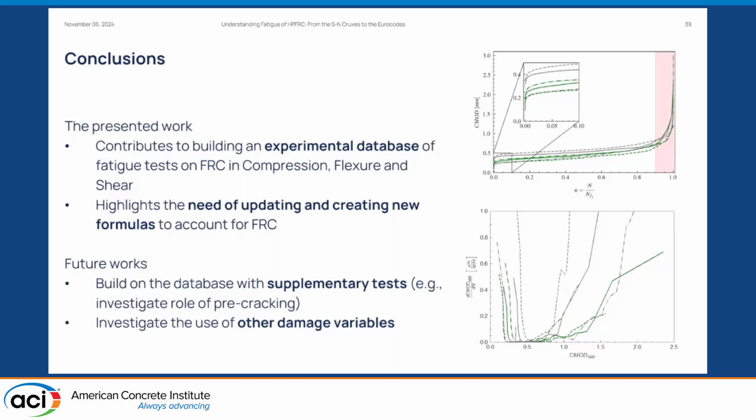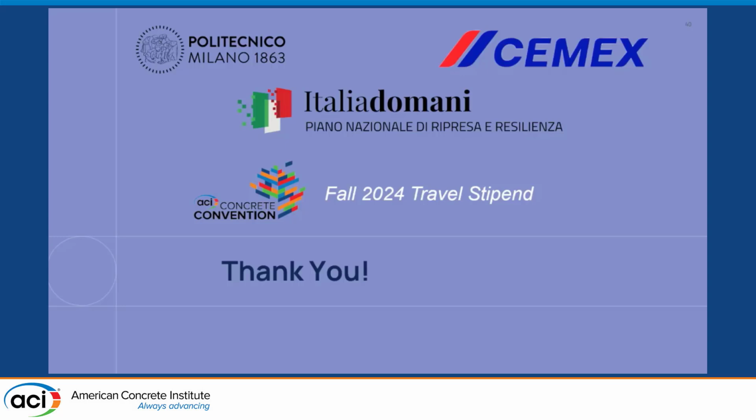On our part, we also started to investigate the role of pre-cracking as well as the role of loading frequency. And of course, investigate other damage indicators. For example, now we are trying to assess the damage based on the accumulated crack mouth opening displacement, you can see on the right, or its rate of opening. Okay, this really concludes my presentation.